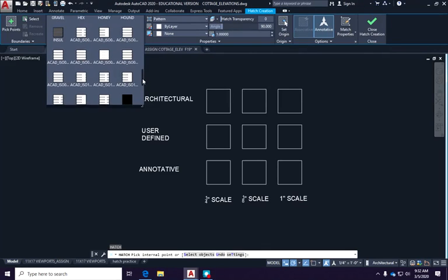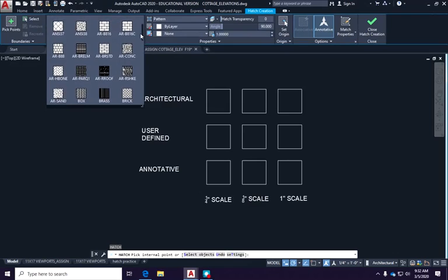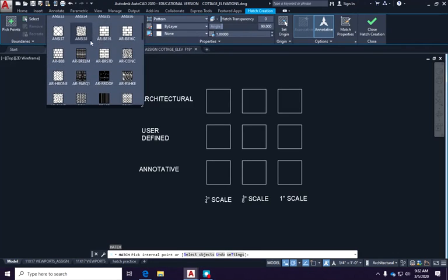So I'm going to scroll up, left click and scroll up. And now I get to there. Here I am. The first one I have is ARB 816. That is an architectural hatch. It's an 8x16 block, like a concrete block. Do not be fooled. It's not really 8x16. Some doofus in ACAD land drew it and said it was, but it's not. So if you're trying to hatch something that looks like concrete block, this looks like it, but it really isn't.